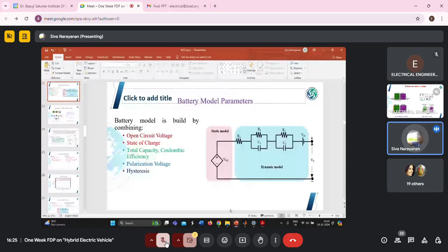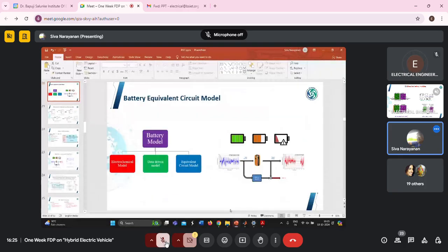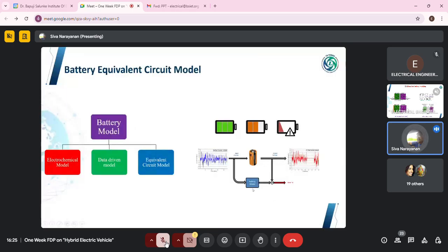Yes, the ECM model and AI based model. Okay, okay, I'll explain with this slide. See, actually, the main idea is here you will be giving a current and you will be predicting a terminal voltage. Here in the battery model, which I have given in this blue color box, will have the enhanced self-correcting model, which is developed by the model which we discussed, or the physics based. It will be purely based on physics based equations. So that equation is fixed. Whatever may be your operating conditions, that equation will not vary. You can give any current and you will predict the terminal voltage.